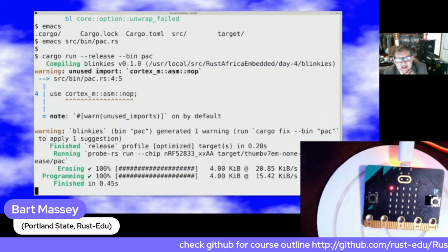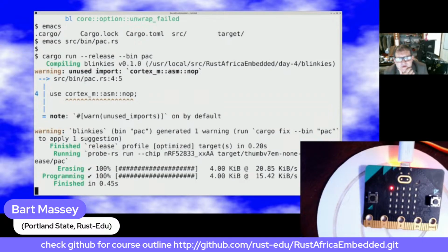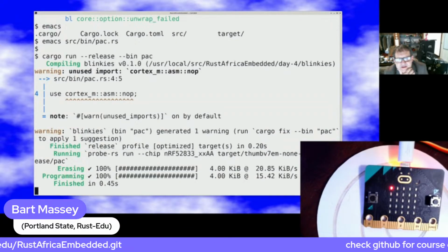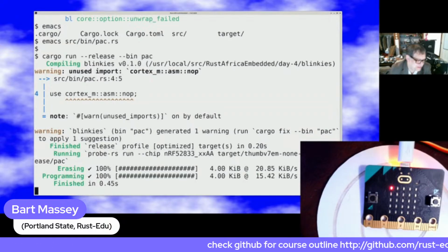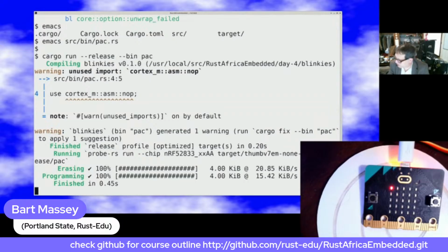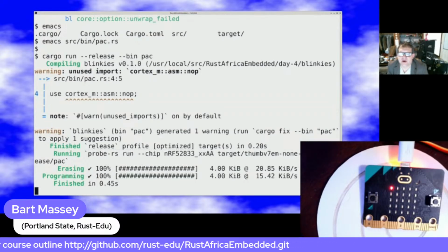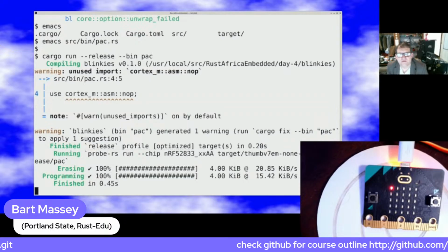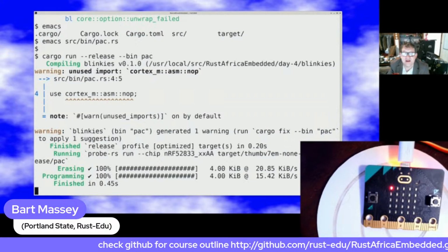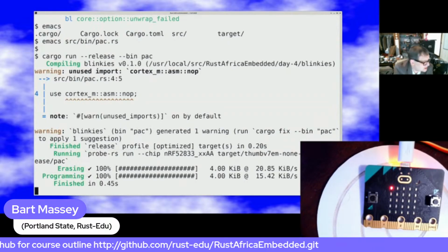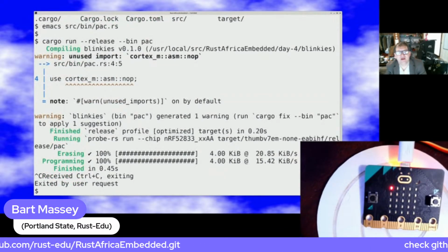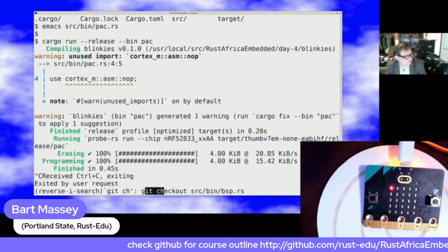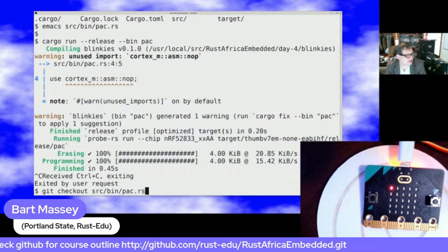But the compiler sees that loop that doesn't do anything, and it just throws it away to make your program faster. And so now we're switching the LED on and off literally as fast as we can, which means that it's at sort of half brightness, because half the time it's on and half the time it's off, but it's working too fast for the camera to pick up, and it's even flipping too fast for my eye to see. If you run this program on your microbit like this, you'll find out that it just looks like it's not quite as bright as the LED is supposed to be. So that's why that no-op was there. It had an actual purpose. The compiler's not allowed to optimize it away, so it has to do something 4 million times. We'll put it back again.